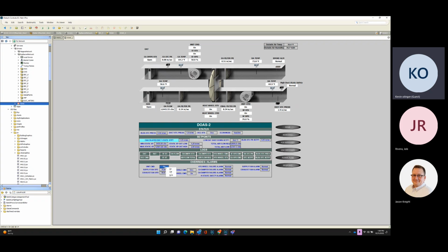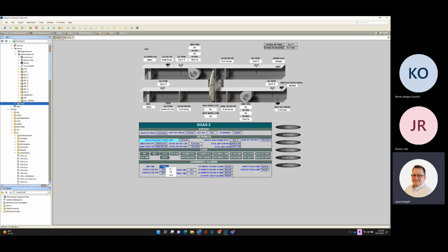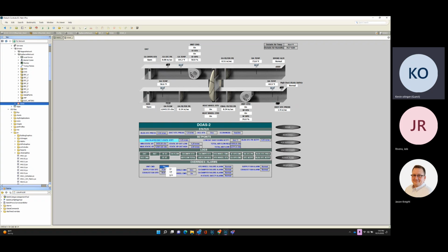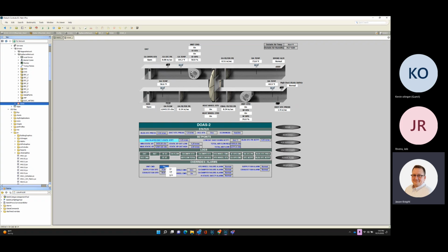And if I understood you correctly before, this unit gets its start command not from a schedule, but from fan coil units, 2 fan coil units coming on, correct? Yeah, there's a global schedule for all the fan coils per sector, like a master schedule, so to speak, that they follow. And then each one of those has their own optimal start stop, whether they start earlier or follow the normal schedule.